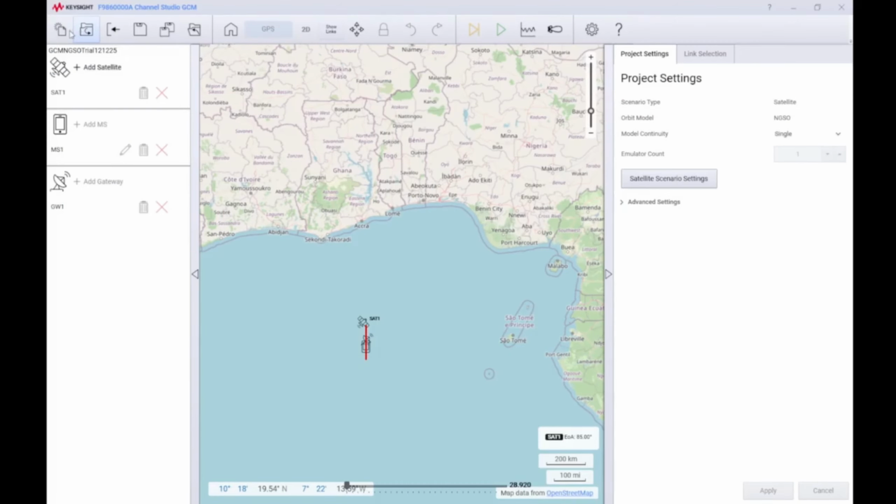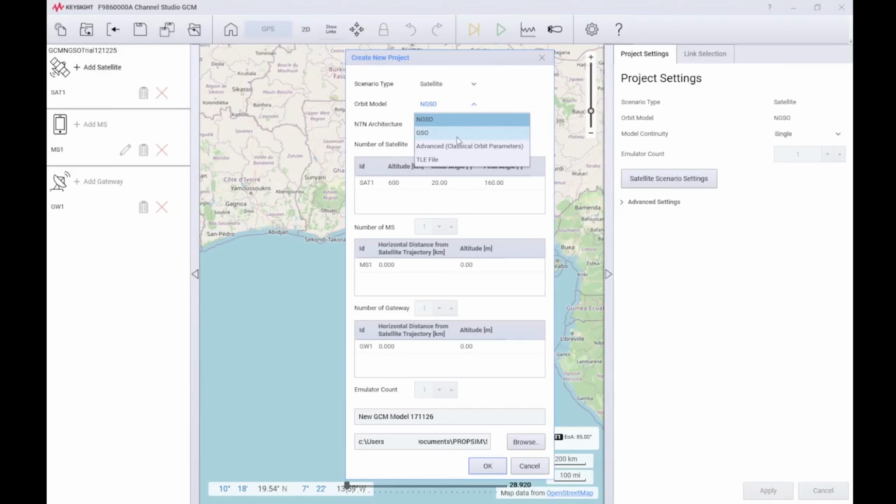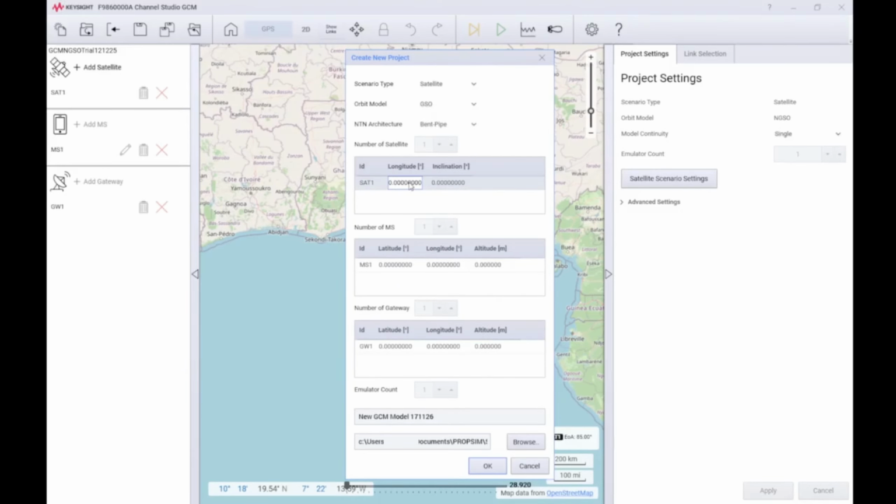So let's try to create a geostationary type satellite, and what are the parameters that you can play around. So you go to satellite, geostationary, orbital, these are longitude. Let's say we set it to 167, which is to the eastern side. Inclinations, this is where you can check with ChatGPT or any help online to tell you more about what inclinations are. So let's say we set it to 40 degrees.